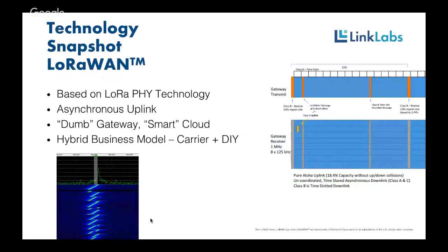LoRaWAN is another technology that is a little different than Sigfox because it can be used both as a public network technology and a do-it-yourself private technology, more like Wi-Fi. It uses this dumb gateway, smart cloud approach, where one or more gateways hear messages and then move the data up to the cloud. It has some limitations just because it's completely asynchronous, or a low-hop protocol, so you can have a lot of collisions and message loss, but it's a very popular technology. The range performance is very good. I put a lot of stuff out about LoRa and LoRaWAN, so feel free to crawl over our website. You'll find more there.